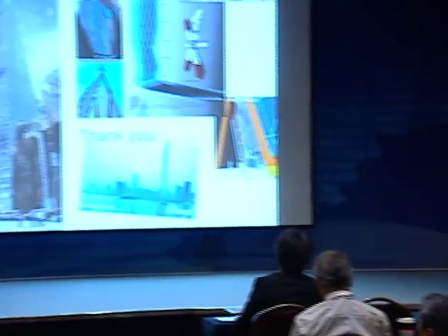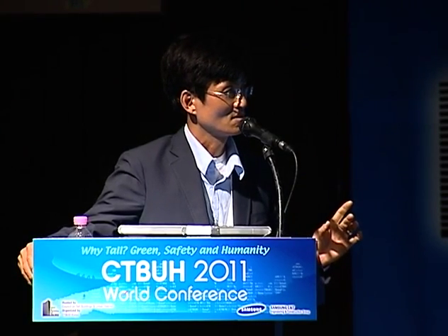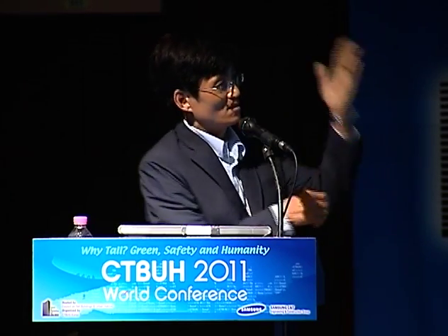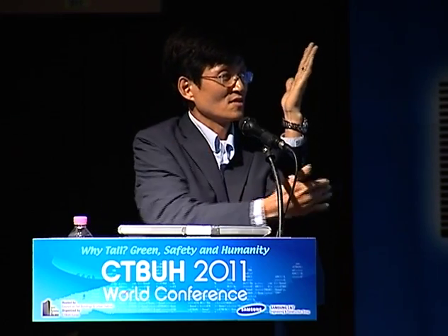Of course, there will be much more stresses based upon this tilting, based upon the gravity load. So that's another concern, actually. There will be more deformation as well as very concentrated stresses at the side of the tilting. I mean, the most vulnerable side of the tall buildings is, if this is the tall building and the wind is blowing in this direction, this side, right?